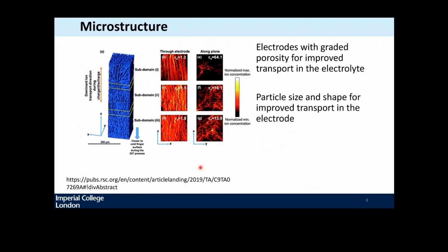So this is a group in Oxford who does gradient batteries. So they look at how they can create electrodes with different porosities to achieve better transport of ions, and thus better performance in the batteries. And again, you could not use an equivalent circuit network to retrieve the effect or predict the performance and sort of choose how to optimize your electrode microstructure for a particular application.